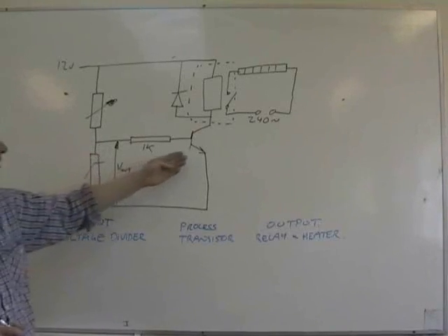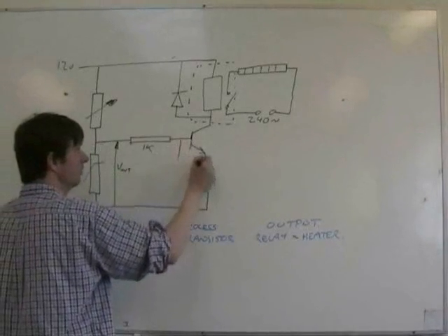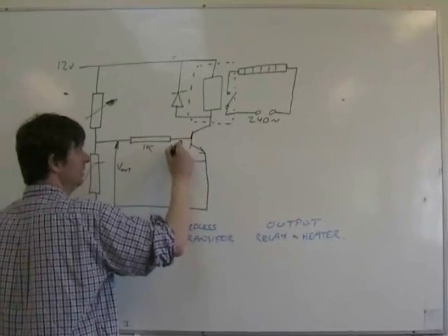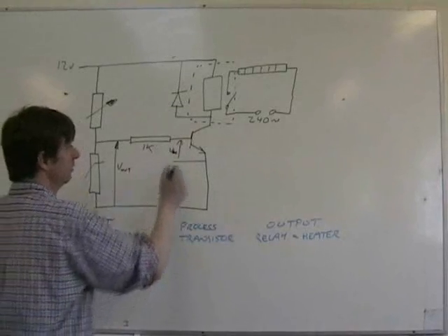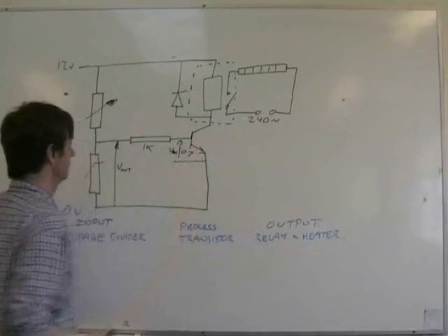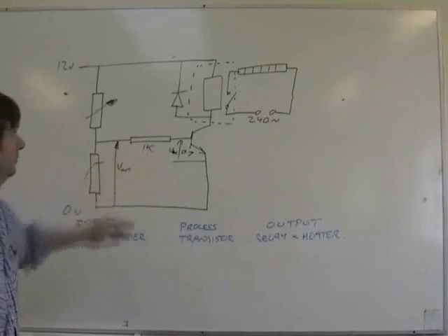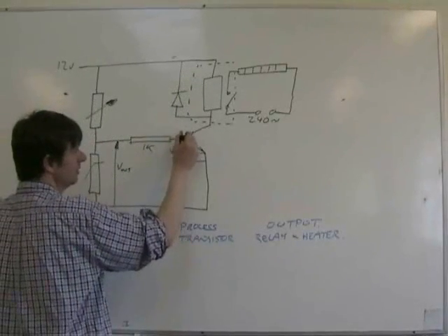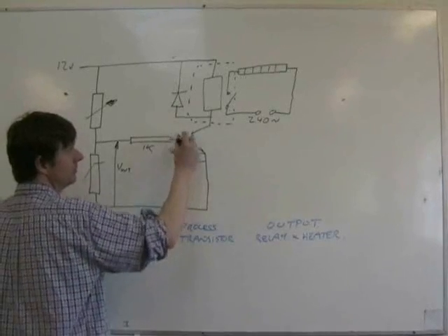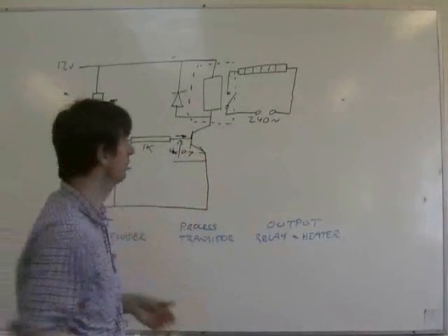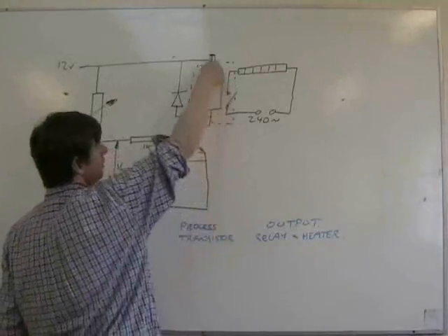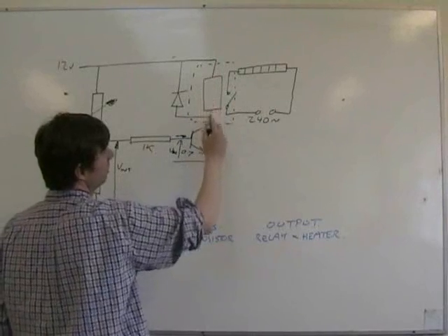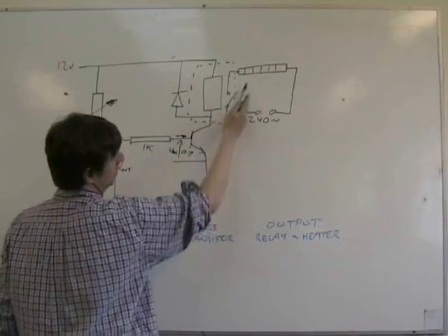The transistor will switch on when that voltage there is VBE, when VBE equals 0.7. The transistor will switch on. A small current flows into the base of the transistor. Now, that small current is probably going to be about 100 times bigger current travels down through here. That bigger current will switch on the relay, pulling the switch and switching on here.